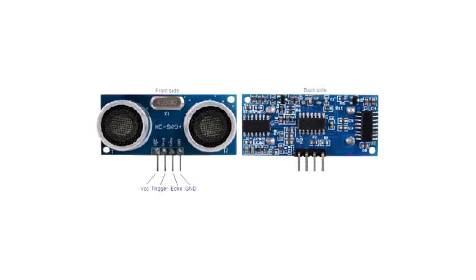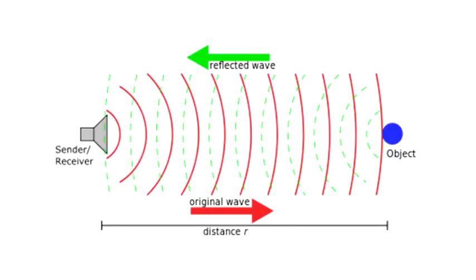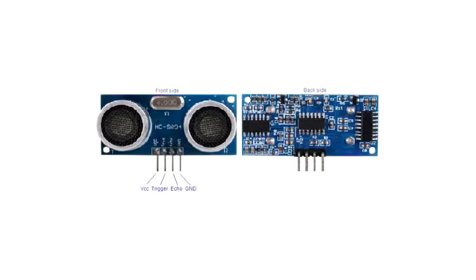An ultrasonic sensor has an emitter and a receiver. The time it takes for the emitted sound to return is used to calculate the distance. The sensor has 4 pins: 2 supply pins, 1 input pin, and 1 output pin. The output pin from the board to the sensor is the trigger pin, which acts like an enable. Once you give it a pulse, it initializes the sensor and it starts to take readings.